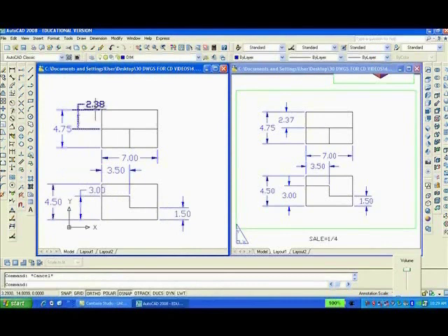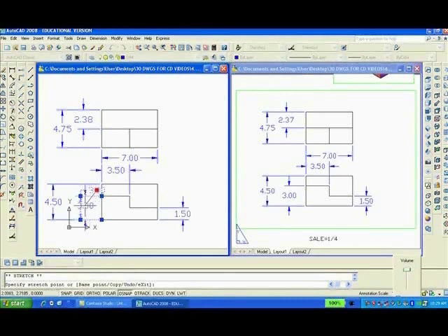These don't look too good, so I'm going to change them. I'm going to take off the object snap and the ortho. I'll click on that dimension, grab the grip and move it in here like this. Pick a point there. That looks better. And I can do the same with this one. With the grip, grab it and move it where I want to put it, like there. Hit escape. Or I can even center it better, since the O snap is off. So that looks better.